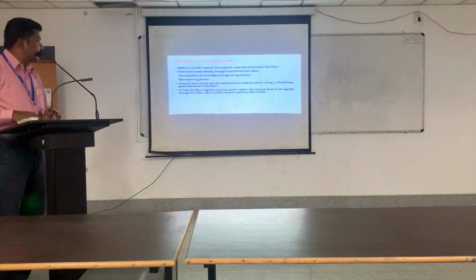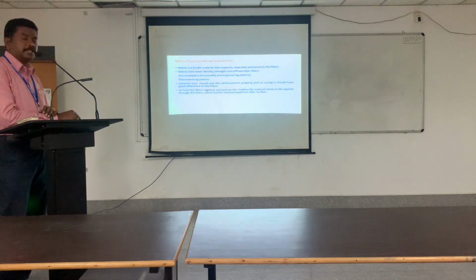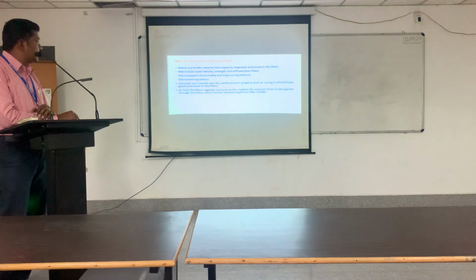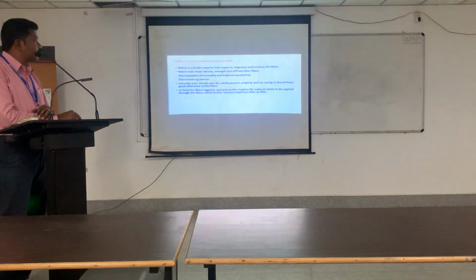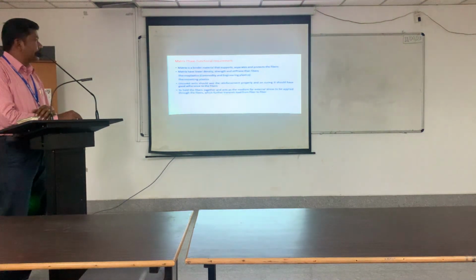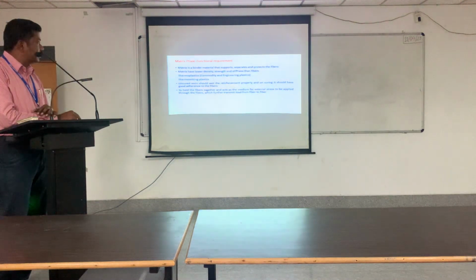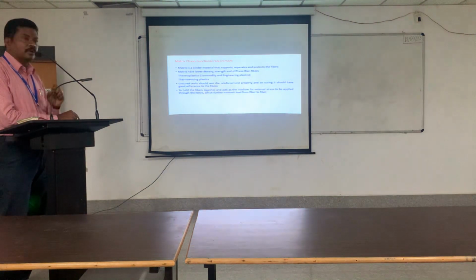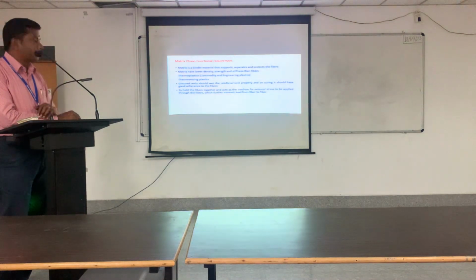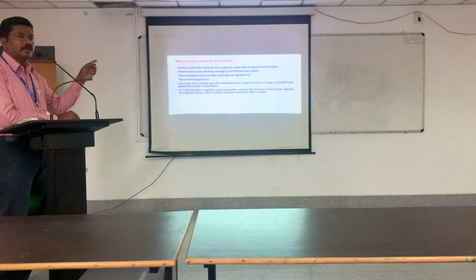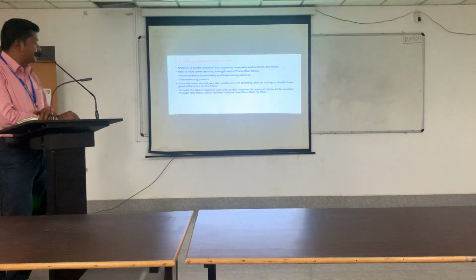So during its uncured resin stage, before curing, before settling, the uncured resin should wet the reinforcement properly, and on curing, it should have good adherence to the fibers. If it is completely wetted, then that will give good adherence, good strength. So for this, the uncured resin will be useful. That is the functional requirement of a matrix material.